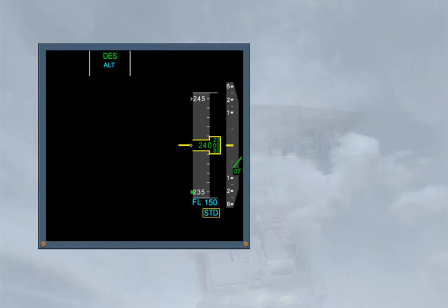When there is a TCAS resolution advisory detection, the vertical speed scale becomes rectangular, and orders to fly the green are displayed as shown. For more information, refer to the ATA34 TCAS presentation module.